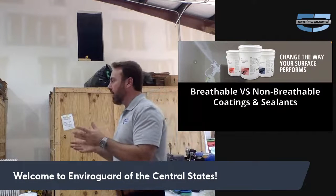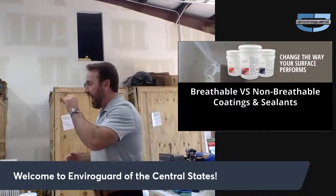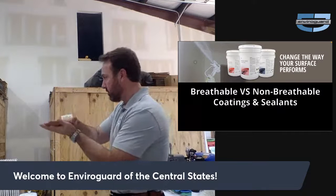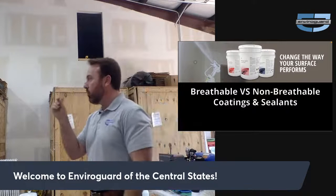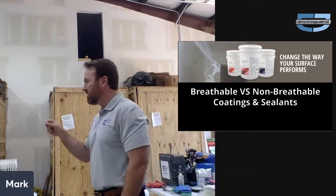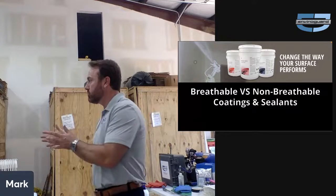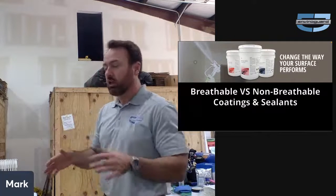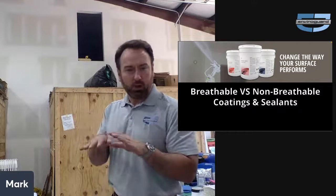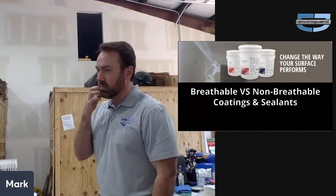When we talk about coatings, we're talking about an adherable product that sits on top of a surface. When we're talking about a sealant, we're talking about a product that penetrates a surface, okay? So to say a penetrating sealant is really a redundant use of terminology. But they oftentimes impart the same or similar qualities, so we're going to include that in our conversation, okay?